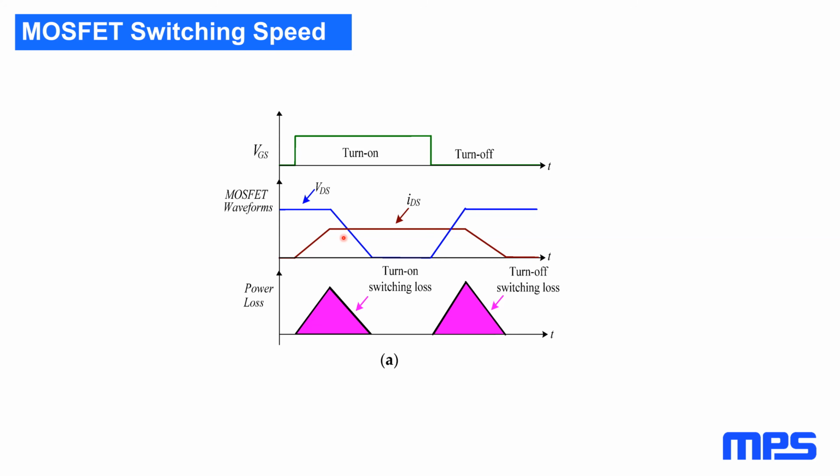Okay, now we've got: is there any consideration of parameters to select MOSFETs to drive a DC motor other than motor voltage and current? Generally not. Secondary stuff like package type and that sort of thing. But really, it's about the voltage and current. And for the voltage, you need to make sure you have some margin. Depending on the amount of current that's going in the motor, you might need a lot of margin.